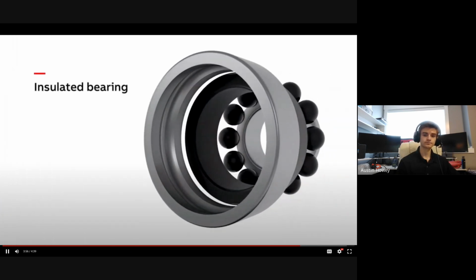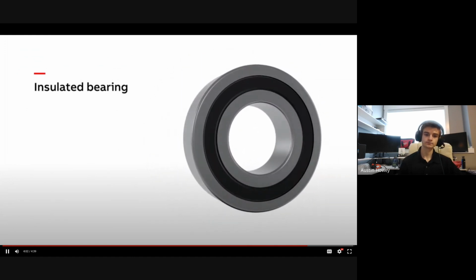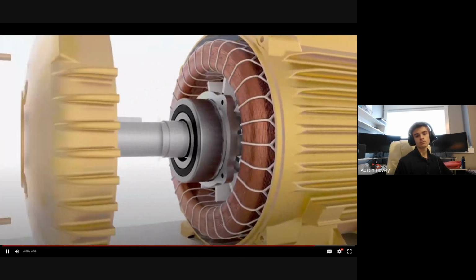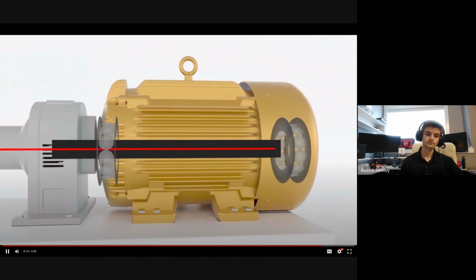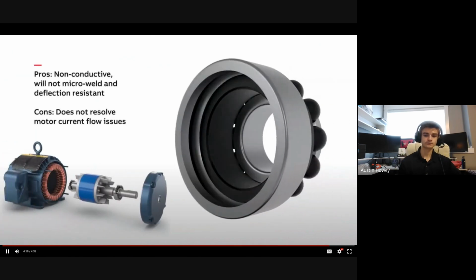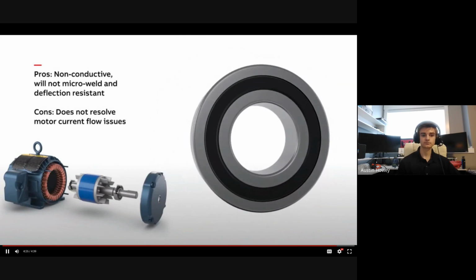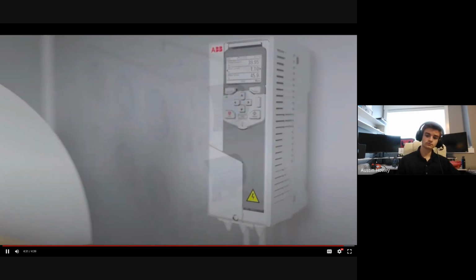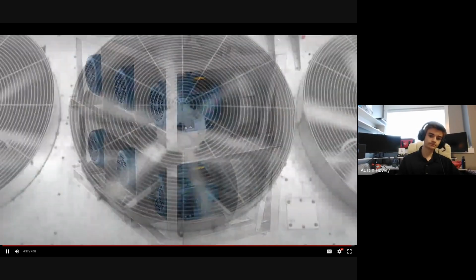Bearings made from an insulated, non-conducting material such as ceramic are another solution to eliminate the discharge of current through the bearings. Non-conductive ceramic materials prevent shaft currents from flowing through the bearings and damaging the motor. Since no electrical current flows through the motor bearings, there is no chance of current-induced wear. However, the current will seek a path to ground, which means it will most likely travel through the driven equipment. Since ceramic bearings will not remove the current from the rotor, only specific applications such as direct drives or equipment utilizing non-conductive couplings are recommended for motors with ceramic bearings.